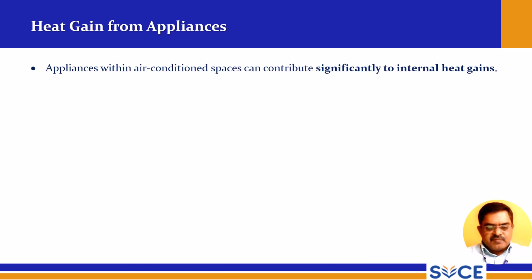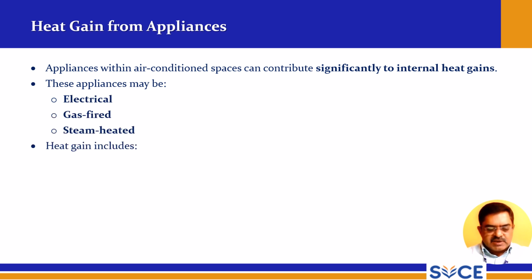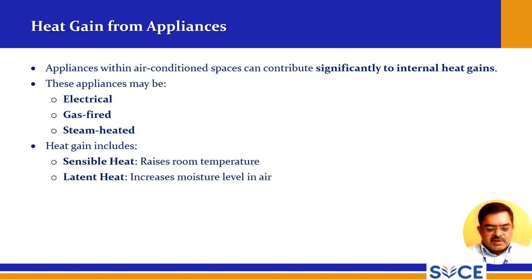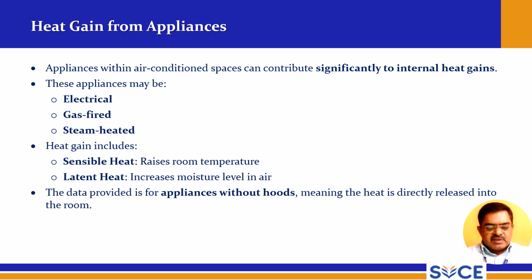And heat gain from appliances. Appliances within air conditioned spaces can contribute significantly to internal heat gains. These appliances may be electrical, gas fired or steam heated. Heat gain includes sensible heat, which raises room temperature, and latent heat, which increases moisture level in the air. The data provided is for appliances without hoods, meaning that heat is directly released into the room.